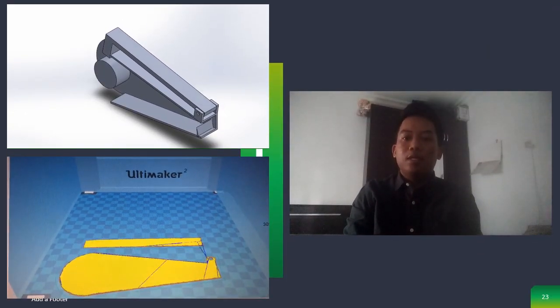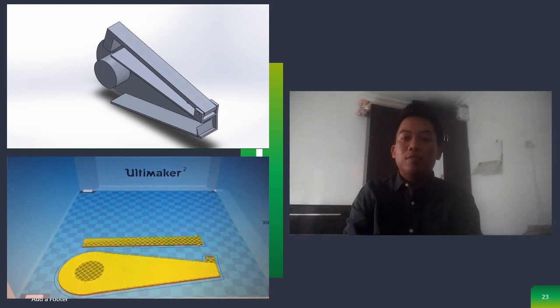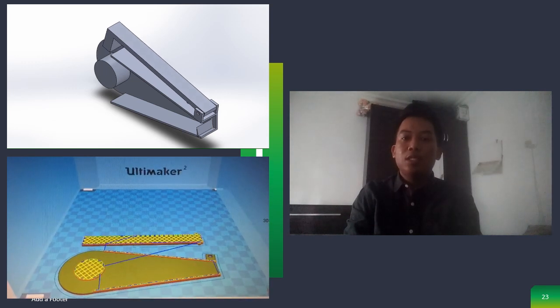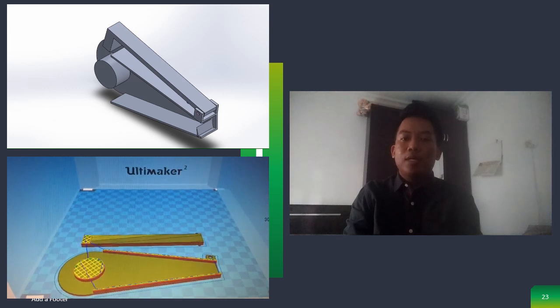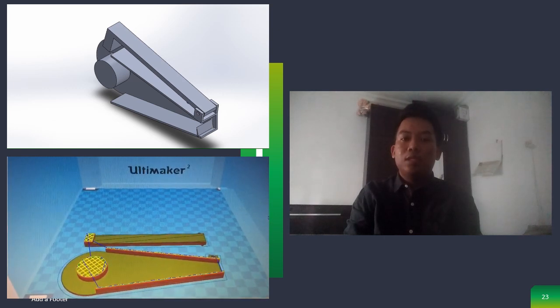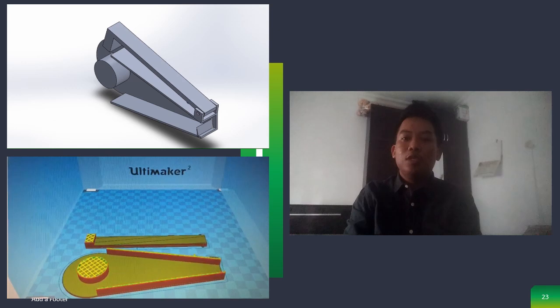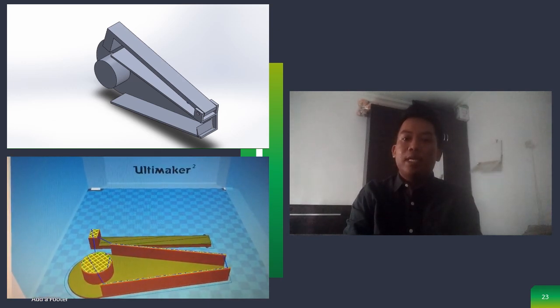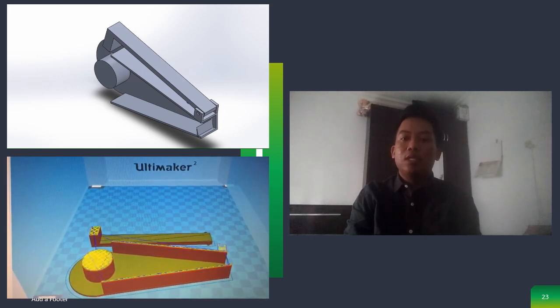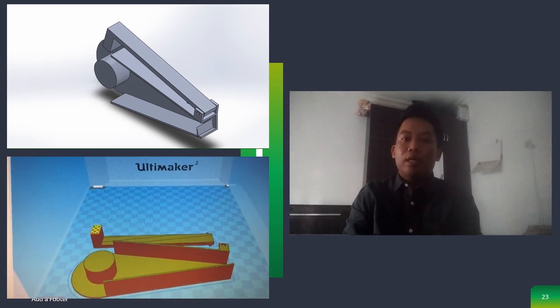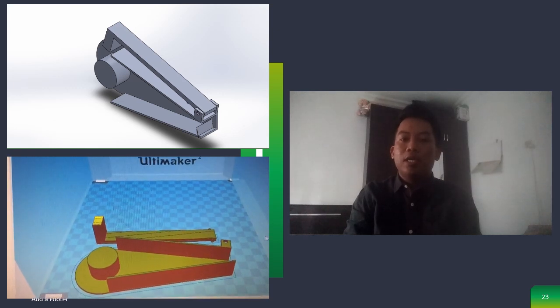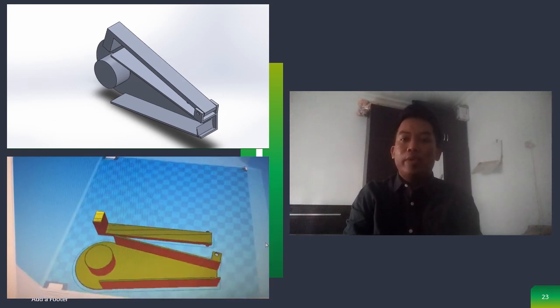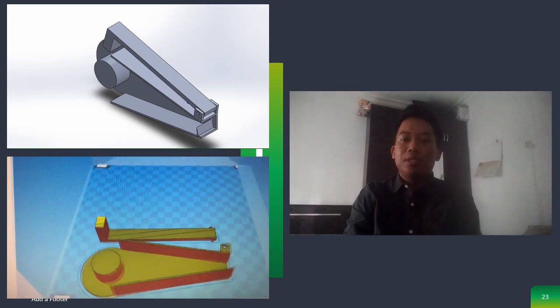Assalamualaikum, I'm Fais, and I will explain the manufacturing process for our product. As you can see, for the main body and handle part of our product, we use 3D printing, and this is the simulation of the 3D printing that we have made, layer by layer, by slicing the solid 3D drawing that we have done earlier. And the other two parts are the tool and the spring. For the tool part, we will use an EDM machine to fabricate it, and for the spring we will use a winding machine to make it into a spring.